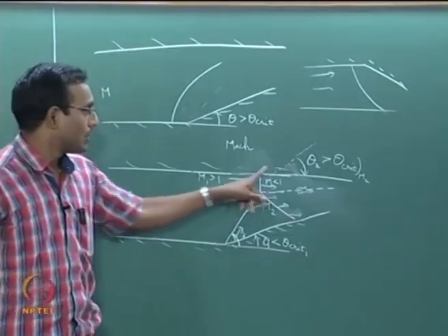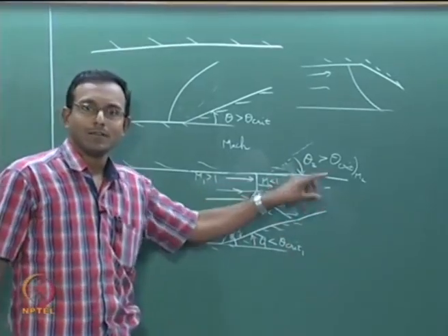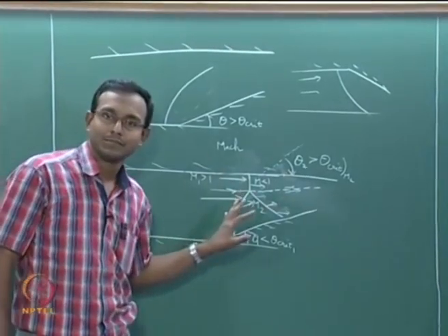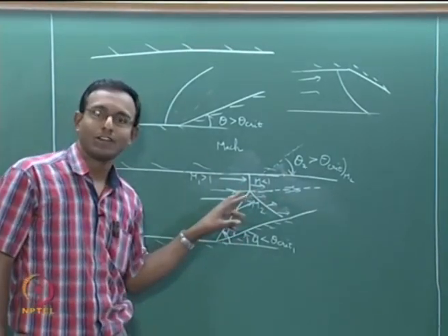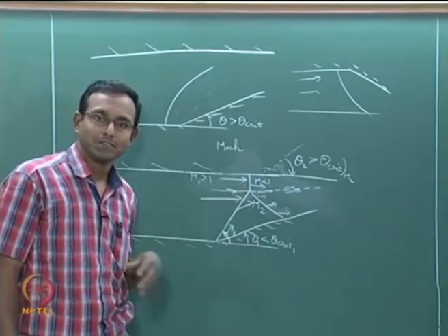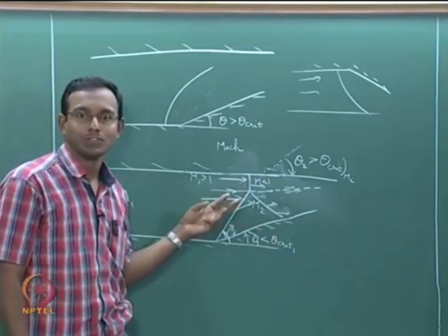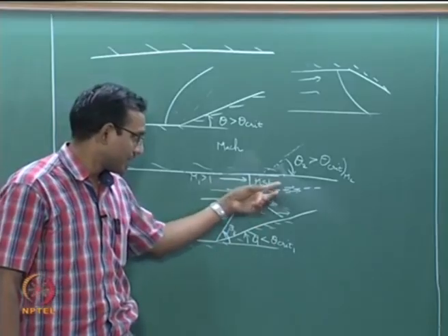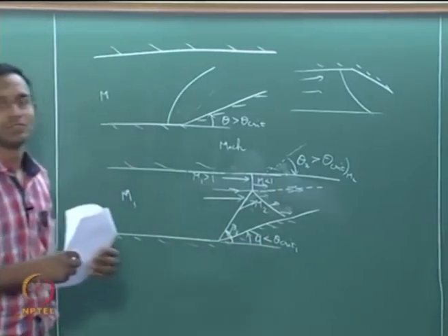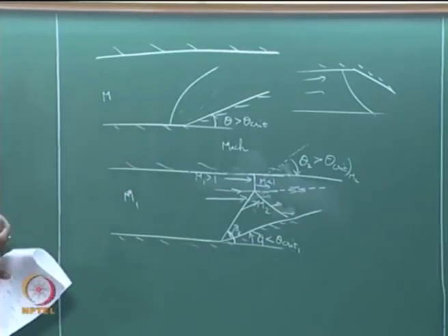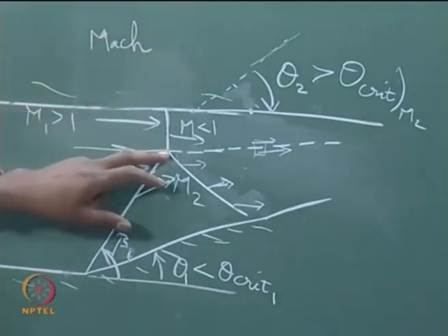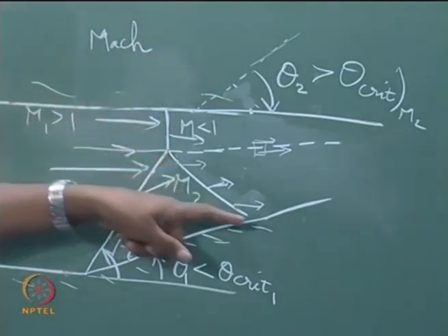Now, overall I am showing you all this, but this particular problem is very difficult to solve from our gas dynamics. I cannot get analytical solutions for this. If I simulate it in some CFD programs or numerical algorithms, I can solve this problem exactly and I will get a nice solution for it. But I cannot give you an expression saying for this much height it will be a normal shock, after that the shock will start curving like a bow shock.